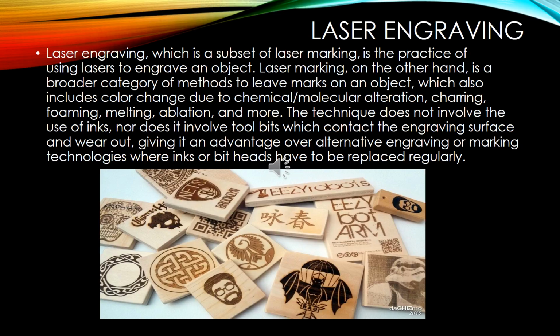results can be achieved. One should avoid large filled areas in glass engraving because the result across an expanse tends to be uneven. The glass ablation simply cannot be depended on for visual consistency, which may be a disadvantage or an advantage depending on the circumstance and the desired effect.